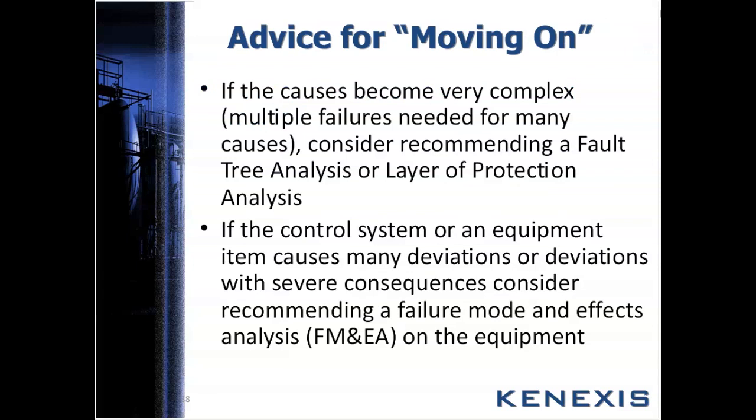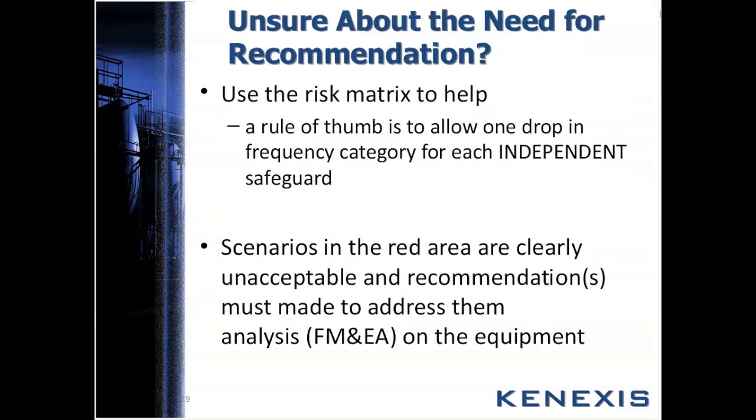Okay, and also if causes become very complex, it's like beating a dead horse. You know, you just have to move on. So you may want to recommend that it goes to a LOPA or a failure mode and effects analysis or some other study if you can't resolve it in the HAZOP.